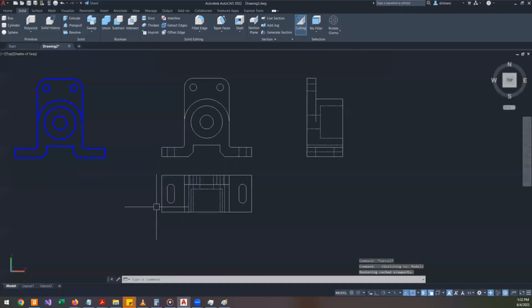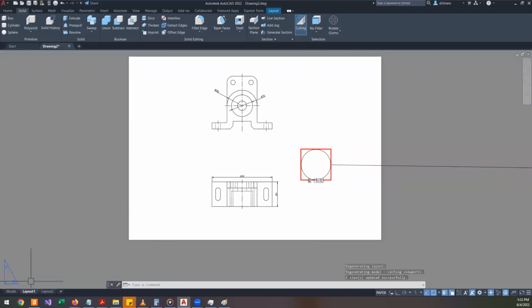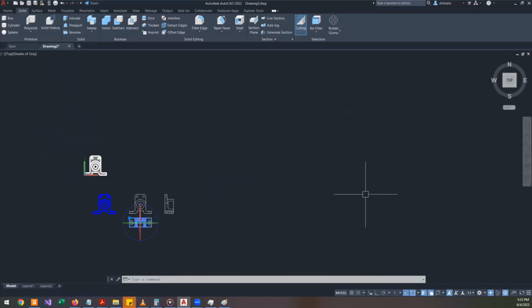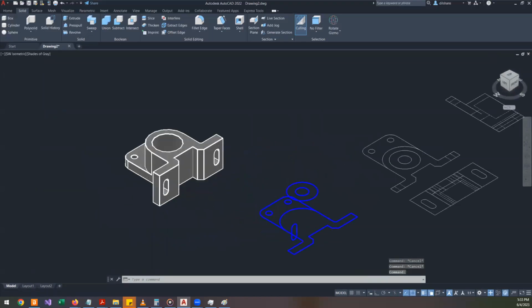It is very easy to manage revisions when you are using layout rather than flatshot. Flatshot is a good command, but it has limitations. Know its limitations and use it nicely, I would recommend.